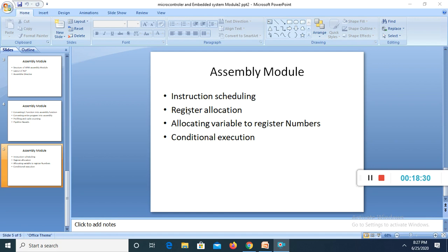If R0 and R1 appear in the register list, then the processor will always load and store R0 using a lower address than R1 and so on. For load and store double word, the LDRD and STRD instructions operate on a pair of registers with sequential register numbers Rd and Rd plus 1. Furthermore, Rd must be an even register number.